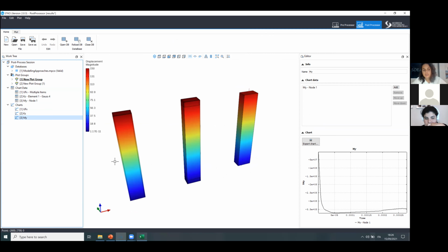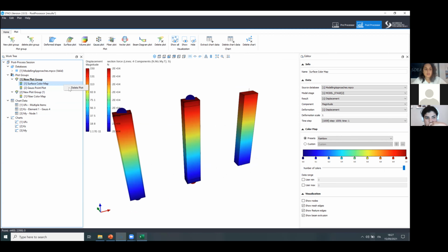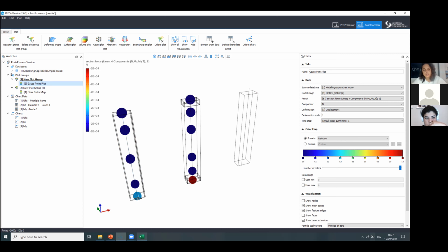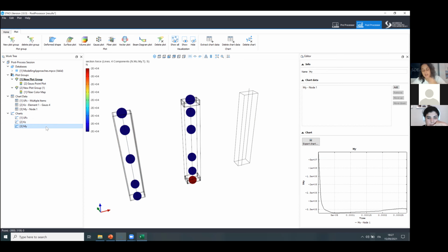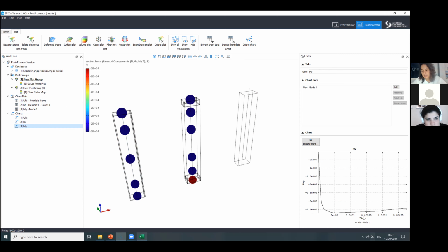So I extracted at the Gauss points at the bottom here, I extracted the curvature kz, and then at the node here at the bottom, I also extracted the moment reaction in the y direction. And so putting those two things together, I copy pasted the values from this graph to this graph, so you don't see the time anymore here, but it actually says this is the moment curvature response, of course flipped because it's a negative moment.